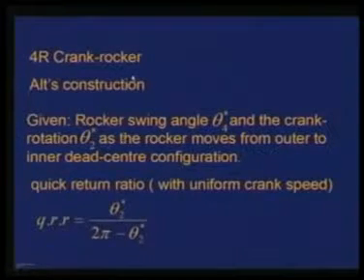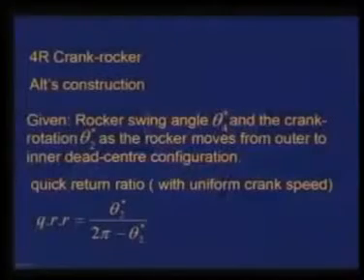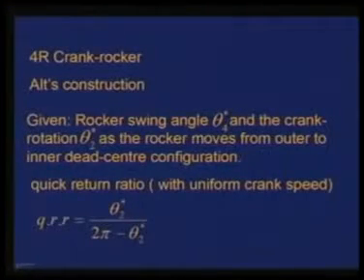Next we shall discuss the dead center problems for 4R linkages, that is the crank rocker mechanisms for given swing angle theta 4 star and the crank rotation theta 2 star as the rocker moves from outer to inner dead center configuration. We shall now discuss the synthesis of 4R crank rocker mechanisms for given dead center configurations.